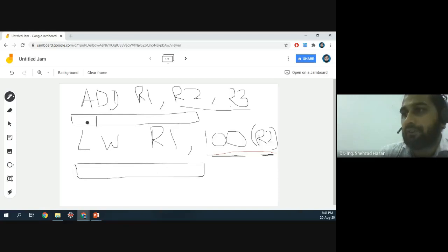Now, they both are going to have opcode at the same position. So they are going to have opcode in the starting, or you can say in the most significant 6 bits. But then there are going to be 3 different register codes in an add instruction that would be named RS, RT, and RD. D for destination here.